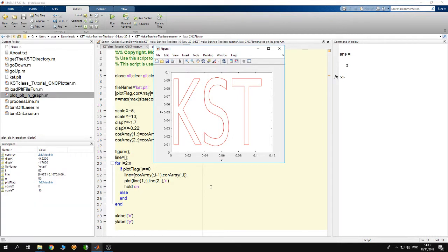So after verifying that your CAD file is plottable, that the corner here is 0, 0, and that the dimension of the box is inside the workspace of the KUKA IIWA, pay attention that those dimensions are in meters. Then you can proceed to plot your CAD file using the KUKA IIWA.